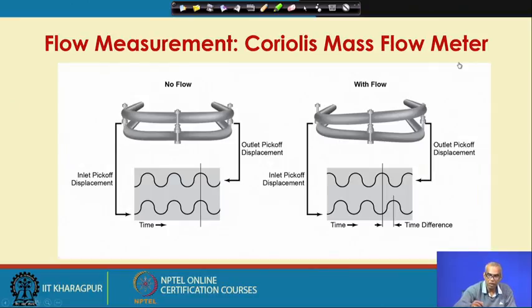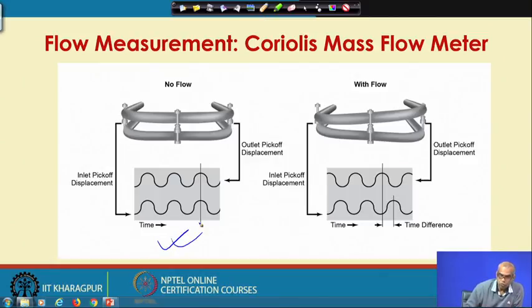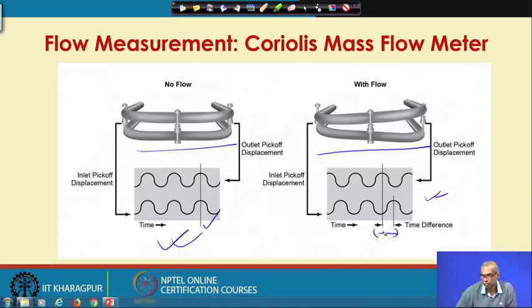So, this is the same. When there is no flow, there is no Coriolis effect, but when there is flow, there is Coriolis effect. There is no phase shift here, but there is a phase shift here. So, this time difference is directly proportional to the mass flow.